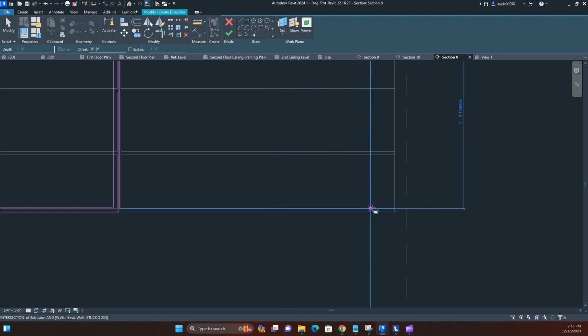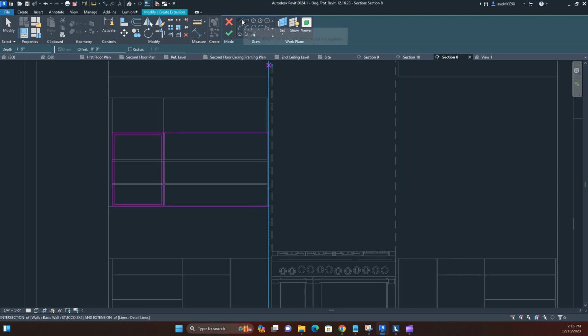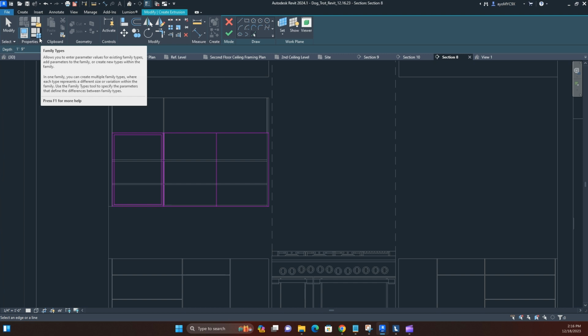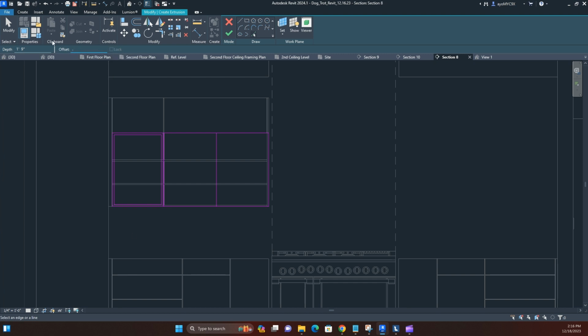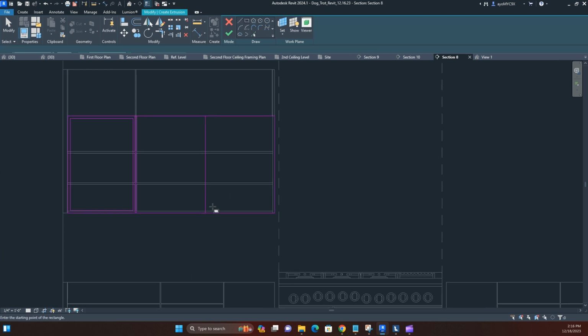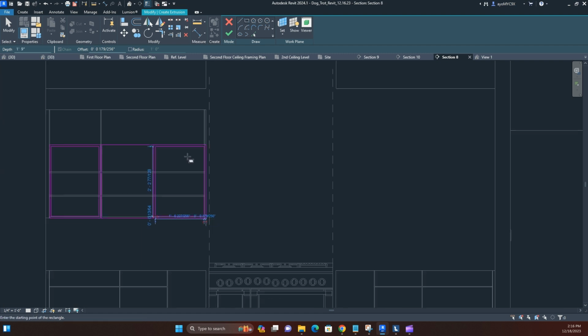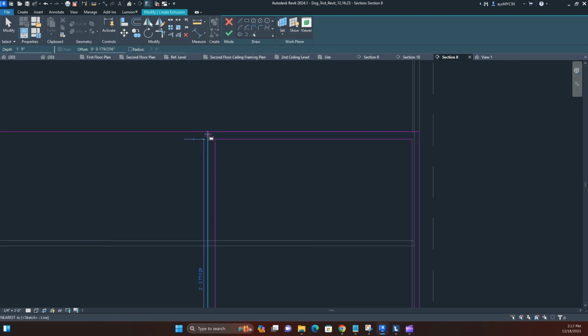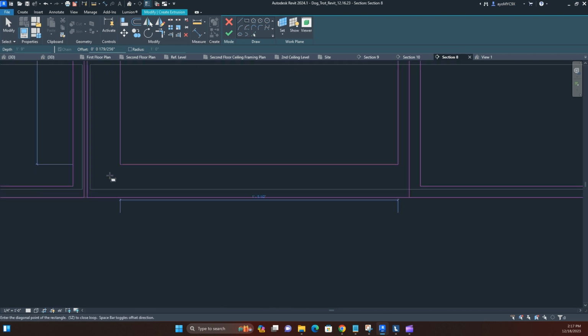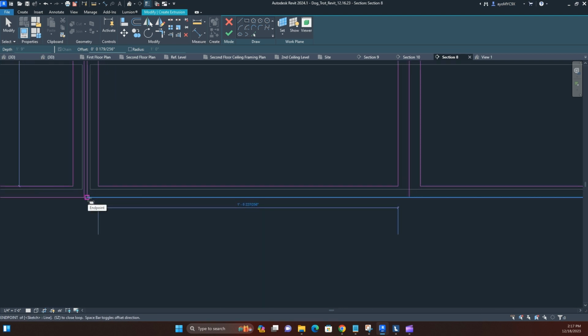So drag it down. For this one, I'm just gonna divide in the middle. Okay, that's what I want. Pick a line for the spacing between that one. You know what? I'm just gonna do the frame for now. 0.7, keep it on the inside. For the right one, do the same for the left one. 0.7 inch, keep it on the inside. Close it off.